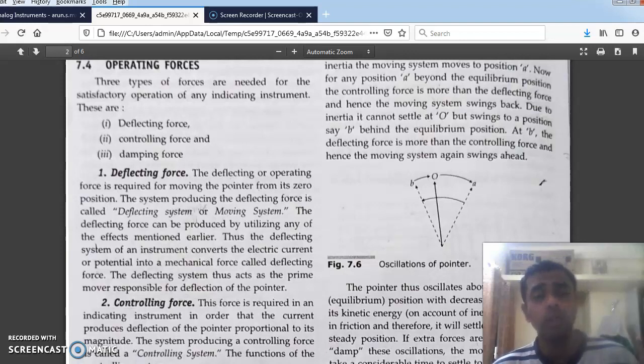Of course, there will be some induced currents in that disk, and that induced current will have its own magnetic field, due to the magnetic field generated inside the disk as well as the magnetic field over the disk. What happens? The disk will experience a force, and it will rotate to obey Lenz's law. So that is what is inductive force.